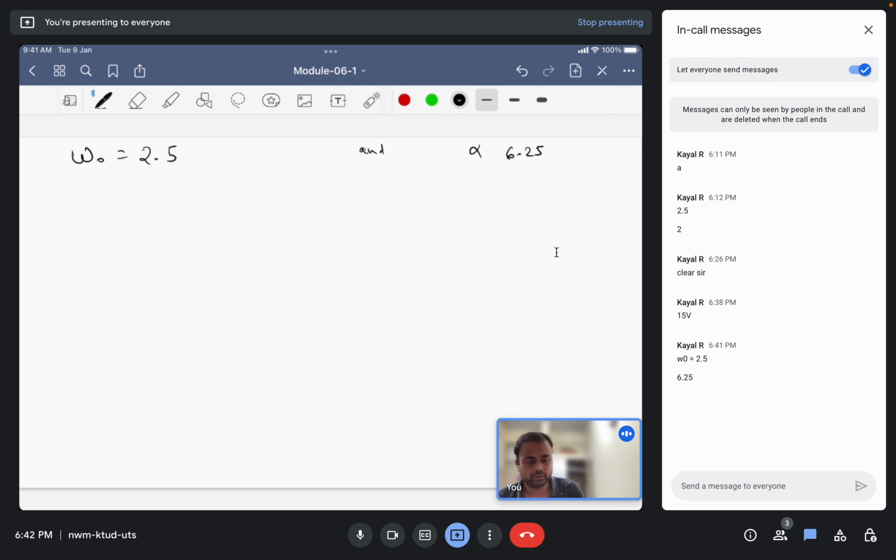So what will be the case, whether this is underdamped, overdamped? Clearly alpha is not equal to omega, so it is not critically damped, but here omega is less than alpha. Whenever omega is less than alpha, the case is overdamped. So the case is overdamped here. For the overdamped case, we'll write the current. So current I of t again will be the sum, that is the forced current I f of t plus the transient, that is the natural current I n of t.